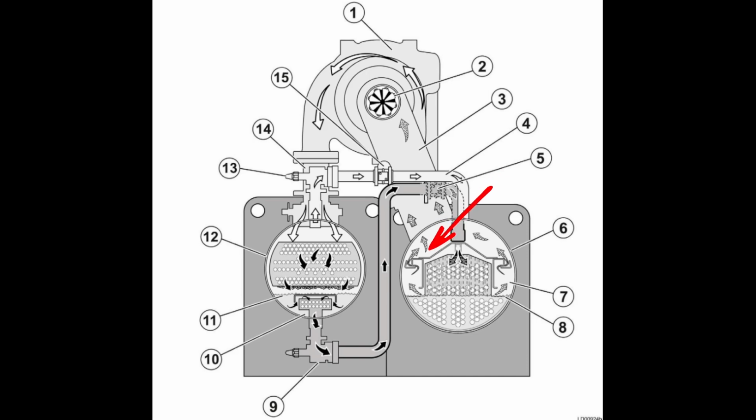That's a normal process. Screws require heavy amounts of oil in order to keep them in safe operation or just make them function to begin with. Either way, despite the style of compressor, this evaporator is not conducive for that oil return process.